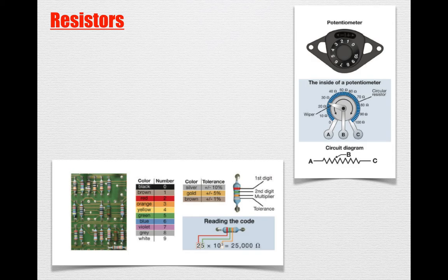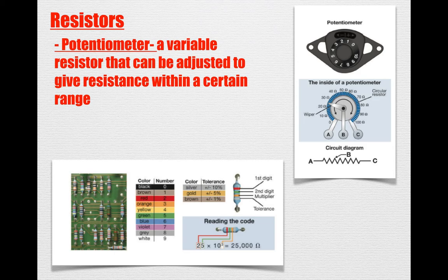Finally, last thing the section talks about more specifically are these things called resistors. So what you guys see on the bottom picture there, there's kind of weird color schematic things. Those are resistors. Now resistors, first of all, we have two different types. We have fixed resistors and then we have variable resistors. What you see on the bottom there, those things are fixed resistors. Because they're so small in a circuit, instead of labeling them with the actual ohms, they use a color coding system, as you can see there, to let someone know what the actual resistance of those particular fixed resistors are.